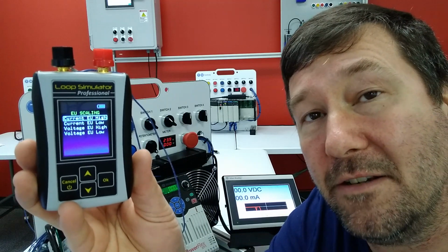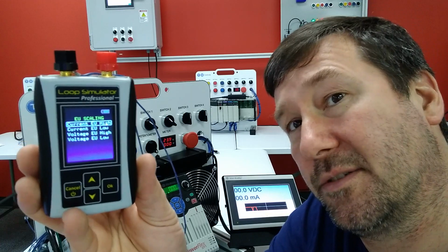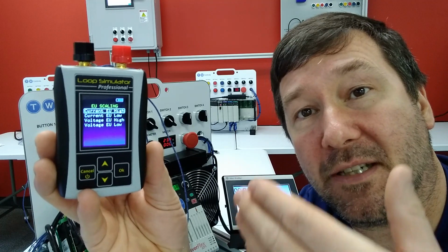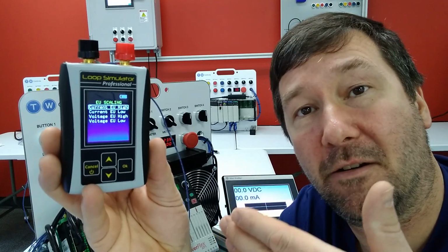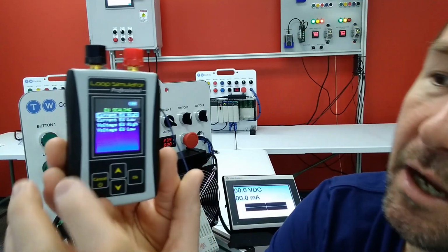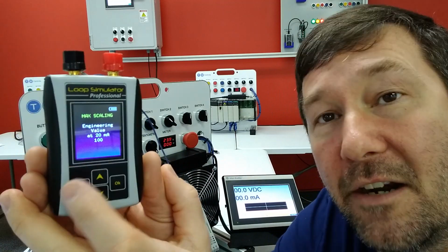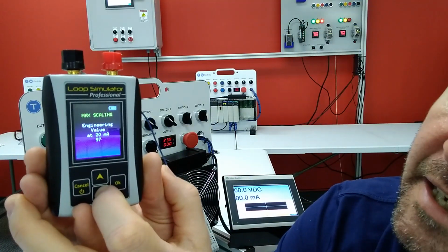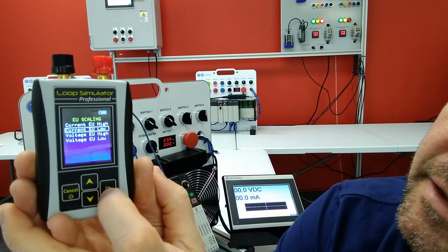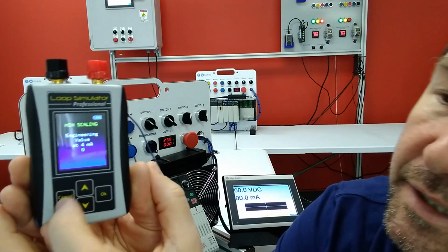And this is very useful when you're trying to work out in your mind exactly what milliamps is what value. Let's say we had an actuated ball valve and 4 milliamps represents 0 degrees or the valve being closed, and 20 milliamps represents 90 degrees or the valve being open. Then we can go to our current engineering units high, and our 20 milliamp value we would want to be 90 degrees. And our engineering unit low for current, we would want to be 0 degrees.